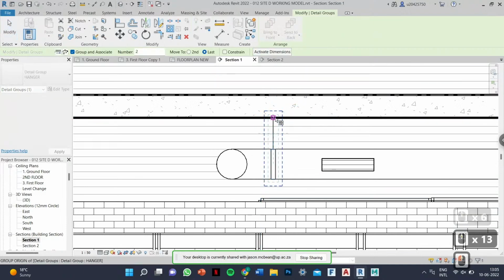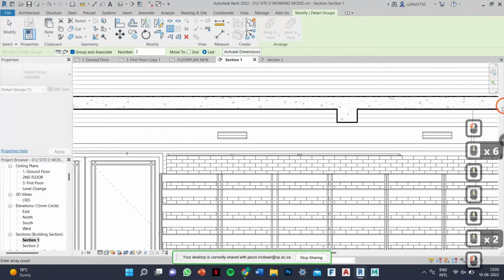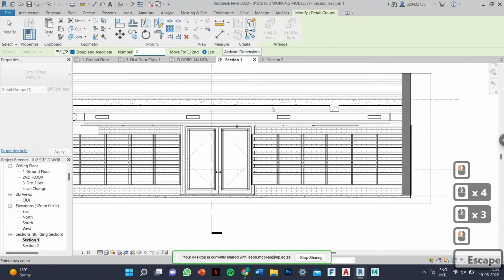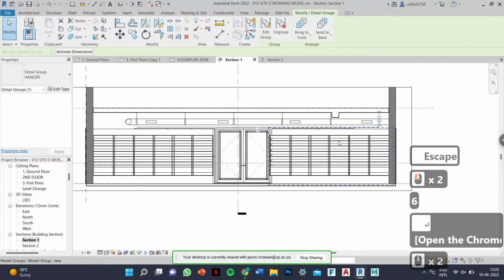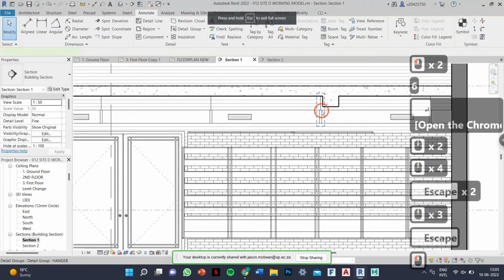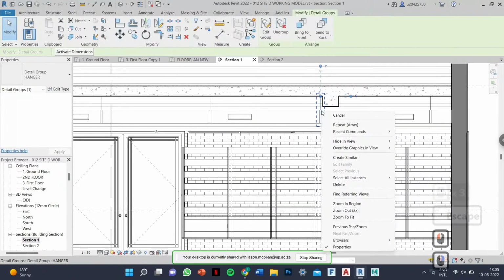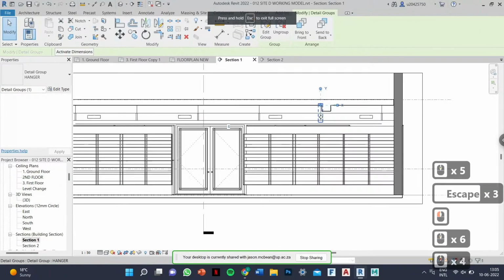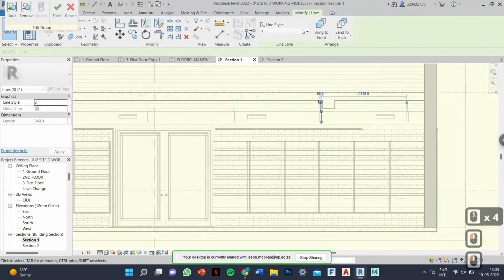Just be careful. From there to there. Check this out. Now I'm going to say that's fine. Now click on this dimension 6 because they might need more of those. Here if there's a clash, you can ignore this from the array. You can actually hide this object from the array. So yes, it's part of the array group, but you can actually go and say edit group. You can actually hide this thing from the array.